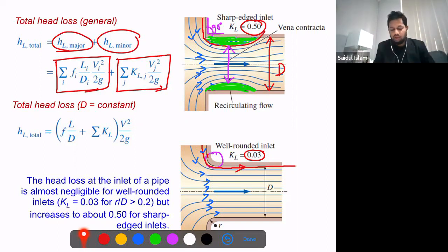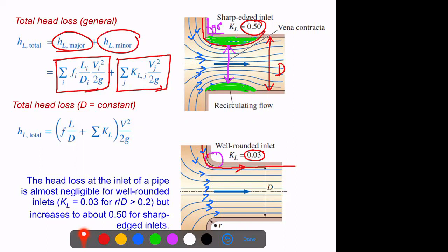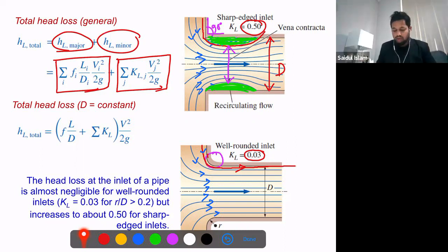The pipe becomes narrow. So now you can remember the Bernoulli principle, and if you know the mass conservation principle, according to the equation of continuity, the flow coming through the inlet and the outlet should be the same. So the fluid velocity will be maximum here. Due to this reason, with less fluid flow surface area, we get higher loss, and the loss coefficient is significant here. On the other hand, when we have a well-rounded shape, it can make some smooth turning, and we have the whole diameter as the fluid flow surface area, and that actually minimizes the loss coefficient.